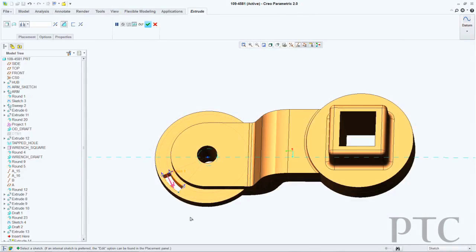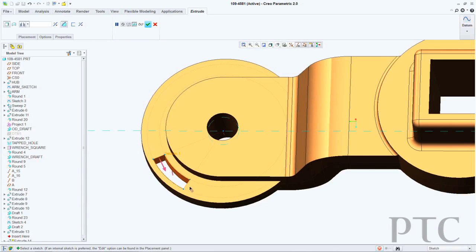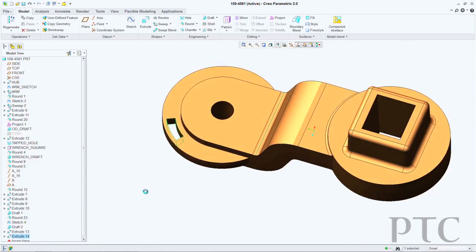In addition, we've also added new geometry commands inside Sketcher, such as the ability to create a center rectangle or a slanted rectangle. We've also enhanced the ability to dynamically regenerate the model. Now I can simply click on a feature, and when I do that, it will show me the dimensions for that particular feature. Each of those dimensions will have drag handles on them. I can directly click on those drag handles and move them, and it will modify just that particular dimension of the section, and in real time update the rest of my surrounding geometry for me.